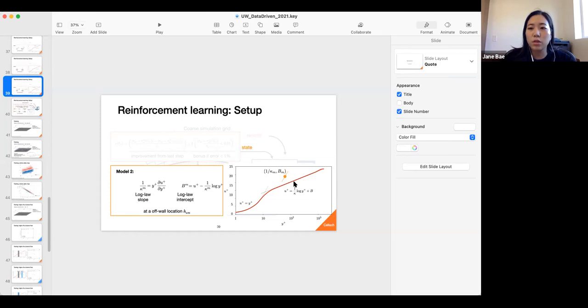It's true that instantaneously the log law is not observed, but the traditional wall models also assume that the log law holds at every instance in time. So basically, the wall model somehow has to expect some sort of universal behavior. In this case, I'm assuming there is some sort of bell curve, where the slope and the intercept of the instantaneous velocity profile are centered around this mean value, which is given by the universal log law.